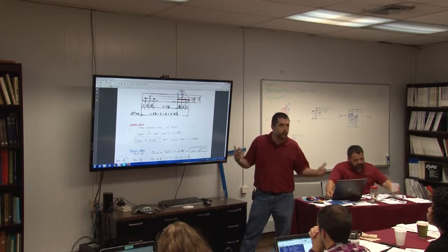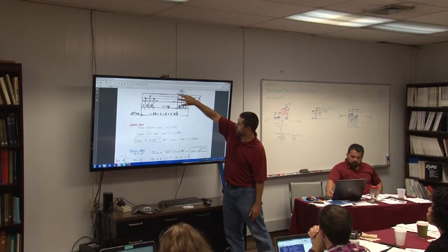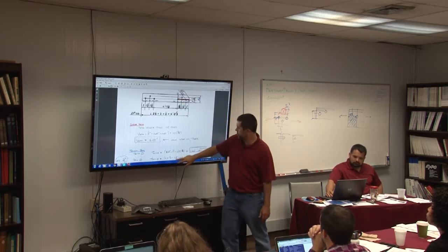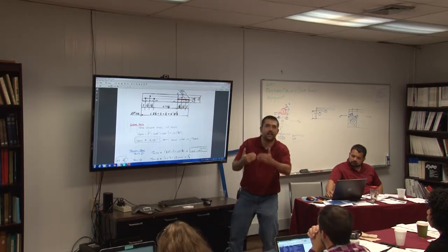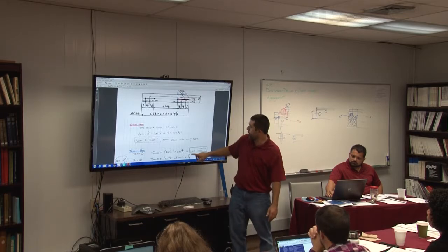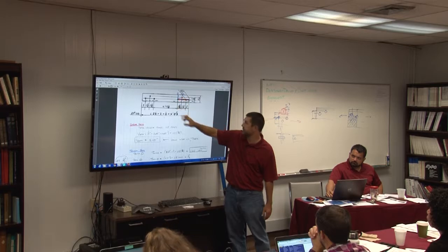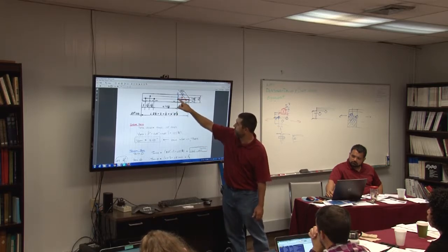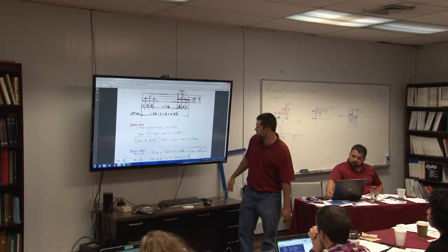Essentially, the way that you do the stagger is you look at the perpendicular distance. So I'm saying it's this 1.5 inches minus 1.5 holes, because I'm cutting through 1.5 holes. And then I'm adding back s squared over 4g to account for this extra length. Same thing we did for net section. So my s is my spacing, 1 5/8. My gauge is 5/8.